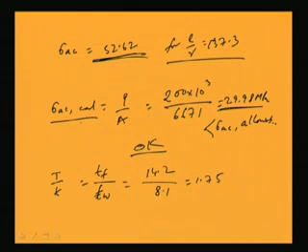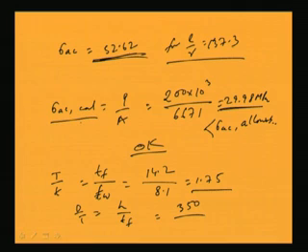So T by t ratio I am getting as 1.75. Similarly, D by T ratio is the overall depth by the thickness of compression flange. Overall depth is 350 and the thickness of flange is 14.2. So D by T I am getting 24.65.